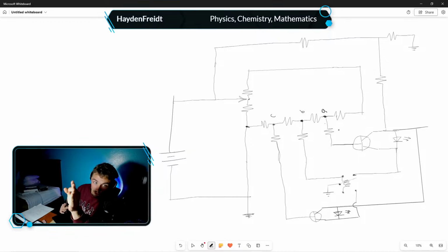and depending on what the resistance is, the magnitude of the resistance will determine the current running through it. But again, this resistor is in parallel with these three, so it experiences the same voltage, with a current running through it determined by the magnitude of resistance. The same goes for these, but we are dropping a resistor every time. So now this resistor here experiences the same voltage as these two, and again this resistor here experiences the same voltage as this one.